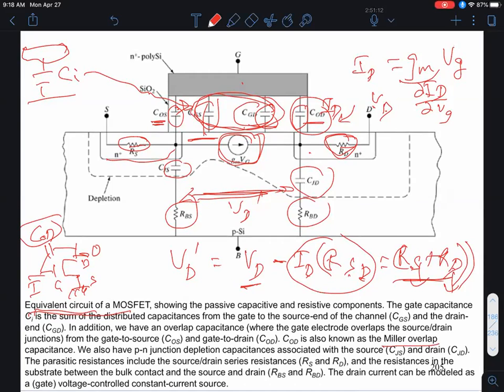And if you remember your circuit classes, such as 438 or even in 302, you'll see that's very bad because that is a negative feedback capacitance, which hurts your high frequency performance, okay? The reason it's a negative feedback capacitance is the impedance of a capacitor Z. I don't want Z to be confused with the width of the transistor.